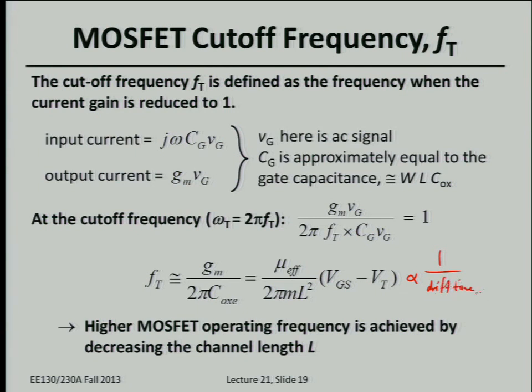That's of the transistor. So what I mean is that you have a MOSFET, in the on state, right, it's biased in the on state. How long does it take for an electron to drift from the source to the drain? Well, it's going to be equal to the channel length divided by the drift velocity, roughly, right? So that's equal to the mobility times electric field, but this is in saturation, right?